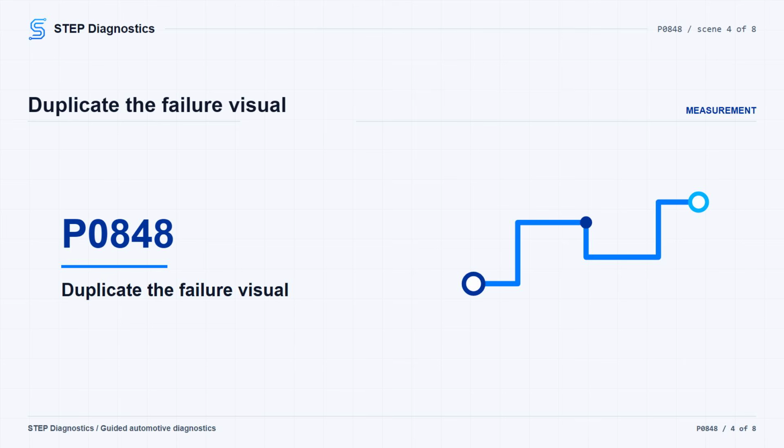If it shows passed, treat it as an intermittent fault for now and inspect for poor connections or loose terminals between transmission fluid pressure switch B and the PCM. If the status is not completed, run the drive condition again instead of jumping ahead.